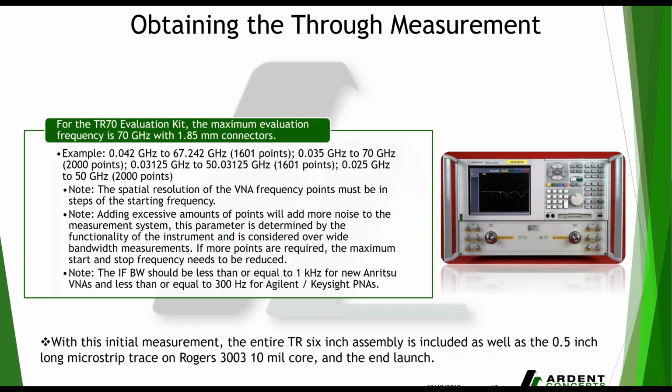Sure, and just an important note here with this initial measurement, the entire TR 6-inch assembly is included, as well as the 0.5-inch long microstrip trace, and it's on Rogers 3003 10-mil core, and the edge launch is included as well in these initial measurements, these through measurements.